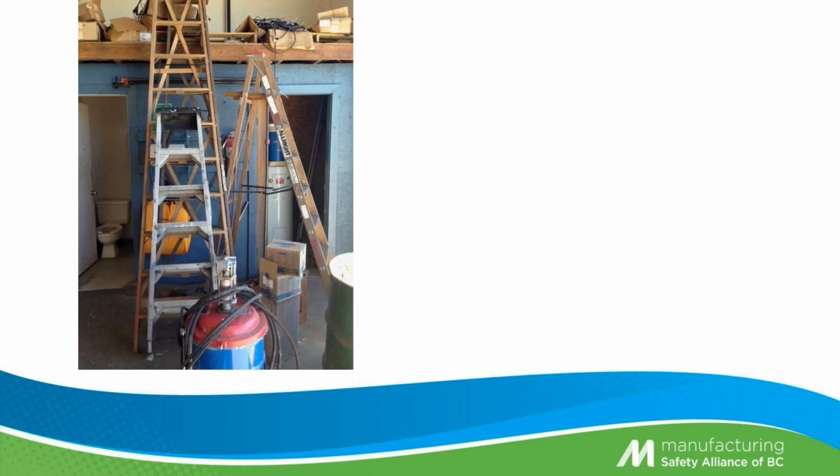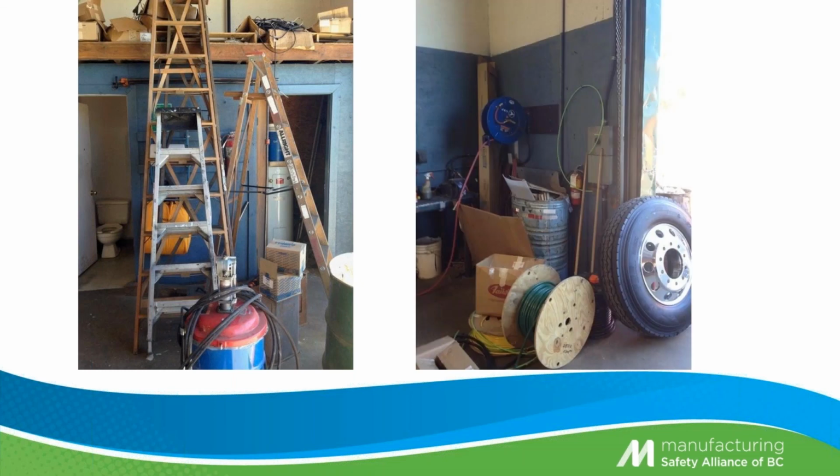We also have the mezzanine level that is being used for storage but has no railings. I just recently had a company last month written up on this because they were loading. If you're putting things up high, there needs to be a railing, because if someone's going to stand up there, then there needs to be a railing or a guard in place. Again, we've got the next picture with the tire there. We've got the fire extinguisher, one not labeled, two buried in a corner.